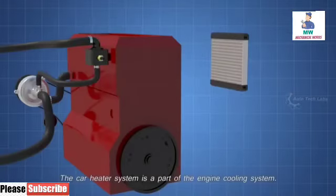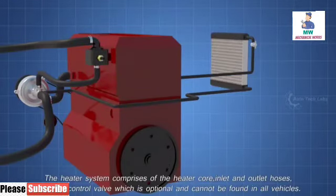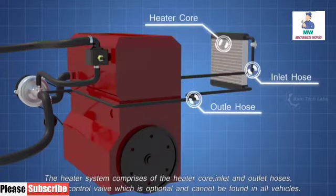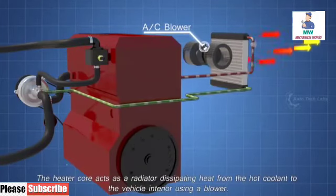The car heater system is a part of the engine cooling system. The heater system comprises the heater core, inlet and outlet hoses, and a heater control valve, which is optional and cannot be found in all vehicles. The heater core acts as a radiator, dissipating heat from the hot coolant to the vehicle interior.